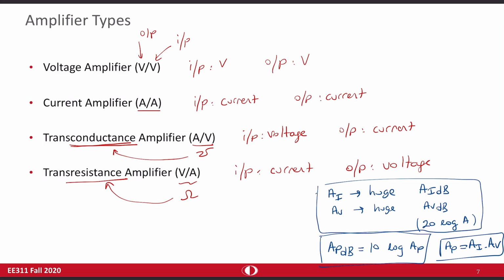And one last thing, when we are dealing with these amplifiers, we assume that the amplifier is linear. So let's say this is our amplifier. When we say it is linear, it means that if you have a sinusoid, sine omega 1t, you get a similar sinusoid but amplified version, sine omega 1t. So the gain does not change the frequency.